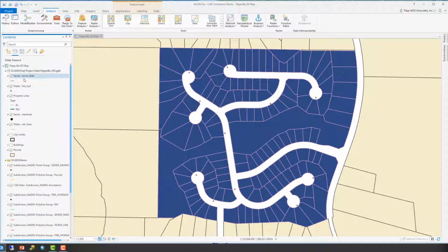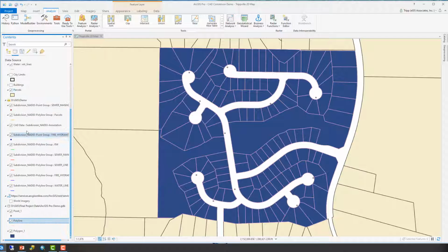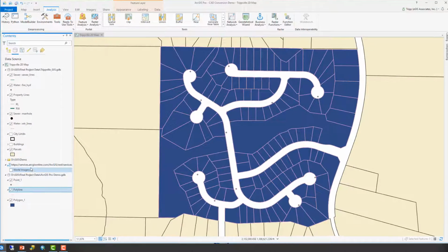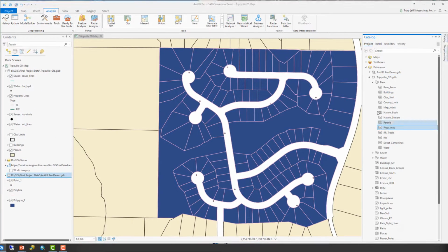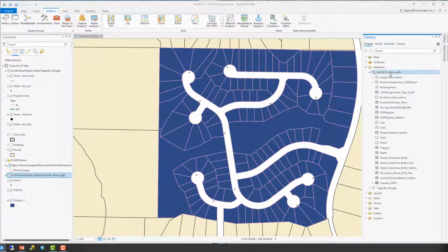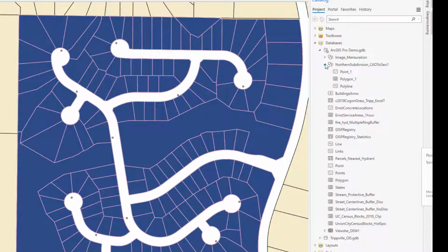And you can see if we go to source, right, that is going to be in, I scroll down past the drawing file. Down here, you can see where it added that in. There was my project database, and there's the feature classes it created. And if I go back into the catalog window as well, here's my project database. I'm sorry, there's the feature dataset it created first off, and then there's the feature classes that it imported into that. So now it's in a geodatabase, and anything we can do with a geodatabase feature class, you can now do with this data, edit it, perform analysis, and so on.